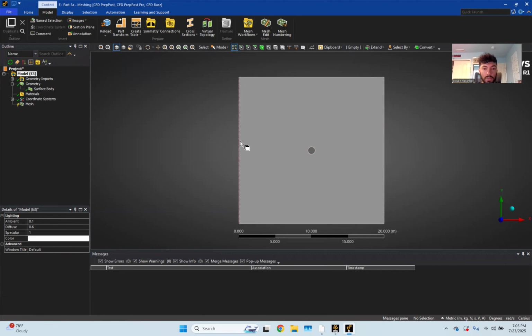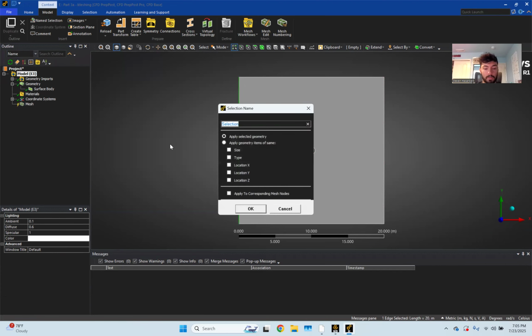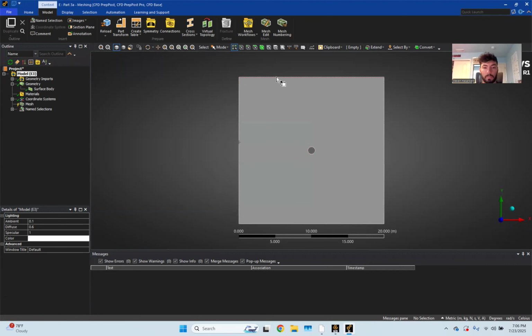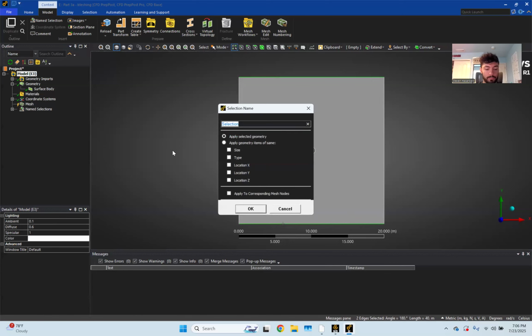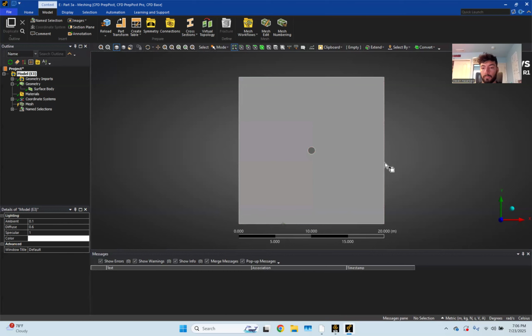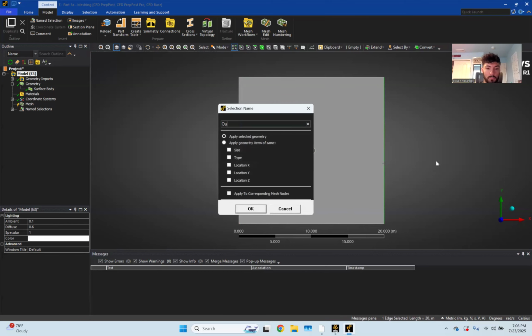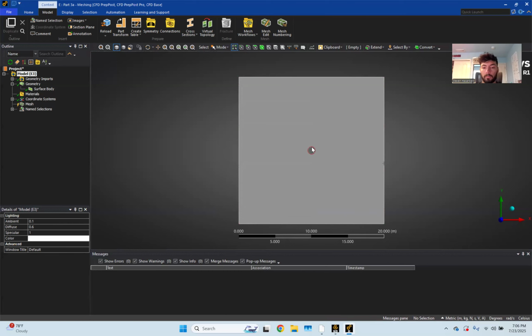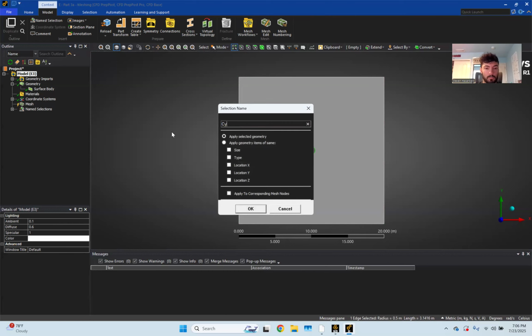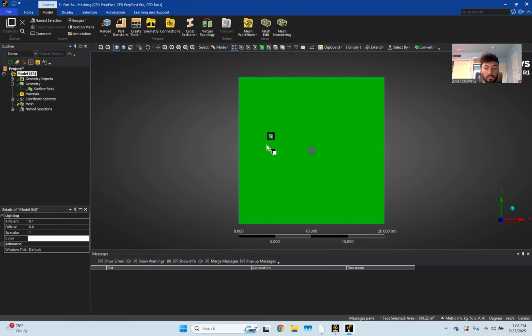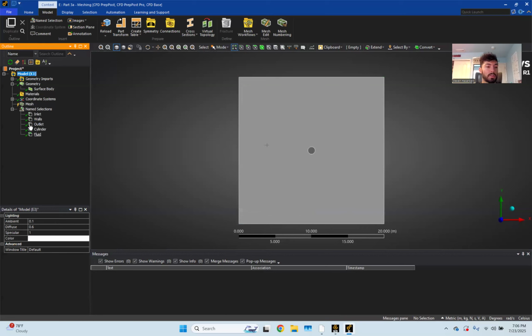So here we can start by naming all of our boundaries, and you can use the N key as a shortcut for it. I'm gonna click on type inlet. You can select 2 edges at a time as well. There we go. And here we can see all of our name selections as well. And now we proceed on the meshing phase.